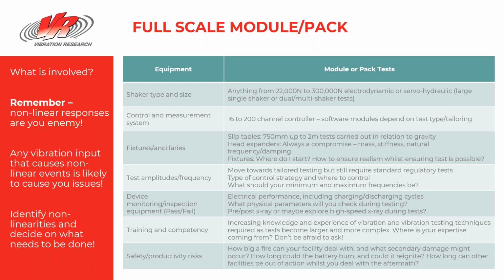So, you'll need to obviously look at control strategies and where to control from, and also look at what your minimum and maximum frequency should be. Again, you're looking at electrical performance during testing, having looked at what your pass-fail criteria are, looking at physical parameters, what you're going to check before and afterwards, as well as are you going to X-ray. Getting battery packs apart is not always easy, so whether you're going to go down the X-ray route to work out what's going on inside.